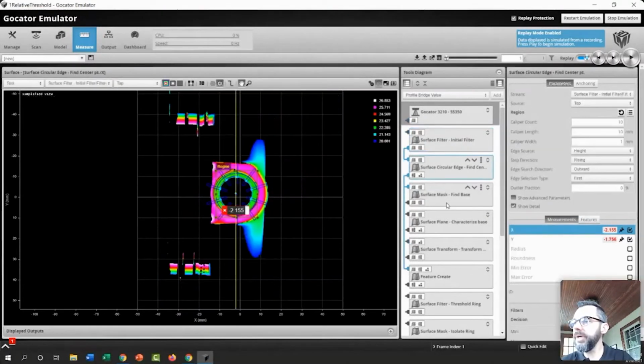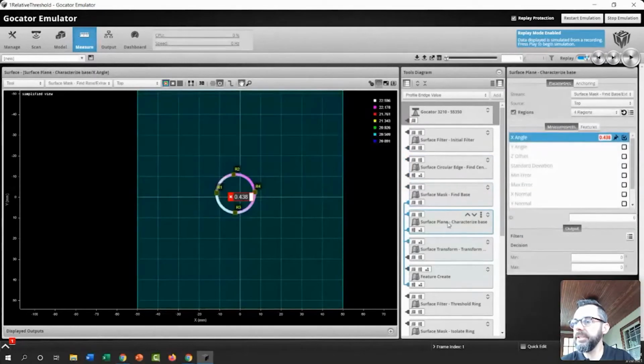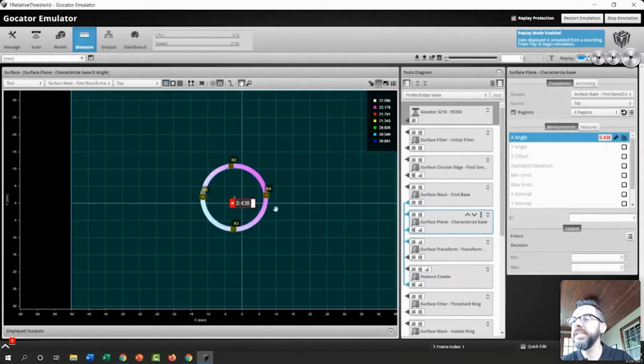So as we go through our chain of tools that's been applied here in our effort to isolate that circlip in there, the first thing that we've done is defined a datum surface in here from which we want to compare that circlip position. And we've done this through surface masking, which allows us to laterally isolate different features inside here. So this is the surface within that stack, if you will, that the customer has chosen as a reference plane from us to start.